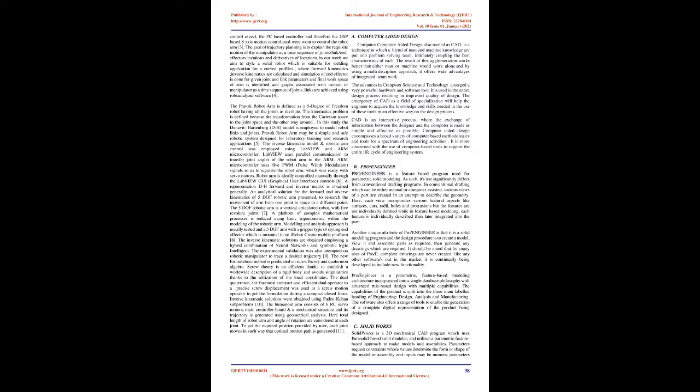A Cartesian geometry arm, sometimes called a gantry crane, uses only prismatic joints and may reach any position in its rectangular workspace by Cartesian motions of the links. By replacing the waist joint of a Cartesian arm with a revolute joint, a cylindrical geometry arm is made. This arm uses a combination of rotation and translation and can reach any point in its cylindrical workspace, a thick-shelled cylinder. If the shoulder joint is additionally replaced by a revolute joint, an arm with a polar geometry is made.